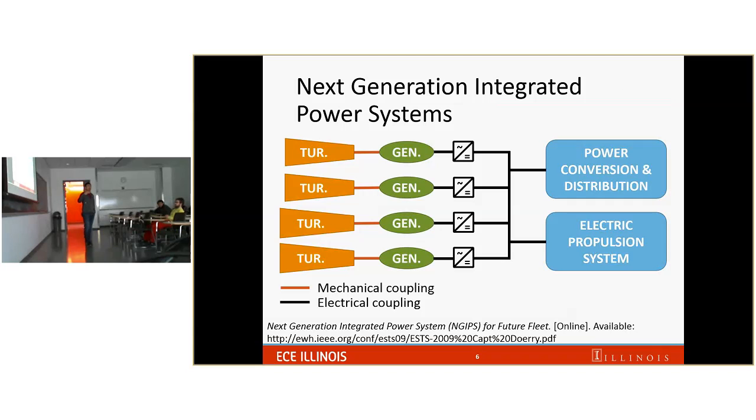A way to collect all the power is to convert it from AC power to DC, collect the DC power on a power system, and then distribute the DC power to the load. So in this application, we always need megawatt scale AC to DC conversion systems.